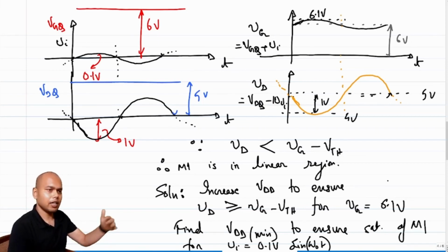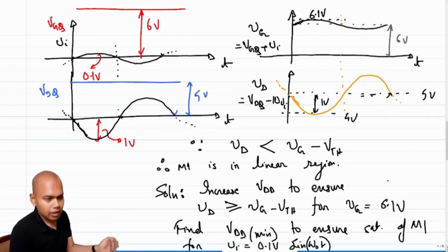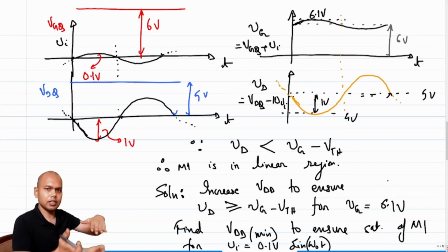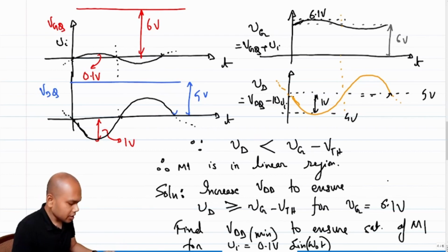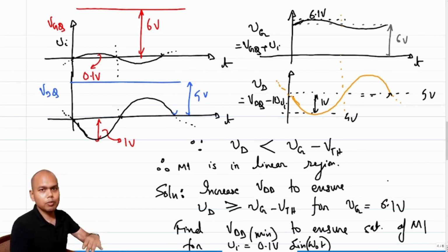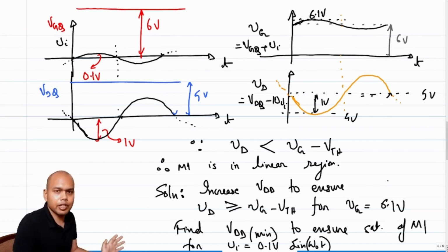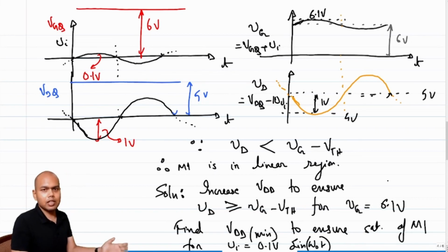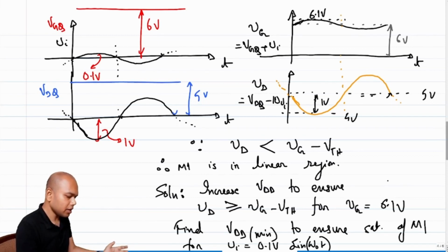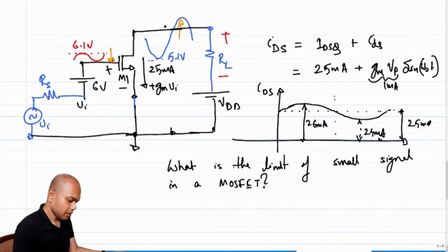When the gate voltage decreases, the drain voltage increases, which means the transistor is safely in saturation. However, there is a chance that the transistor current might reduce so much that it completely shuts off, right? So we need to be careful and see whether that is valid or not. And we saw that under the conditions that we used, it seemed to be okay, right?